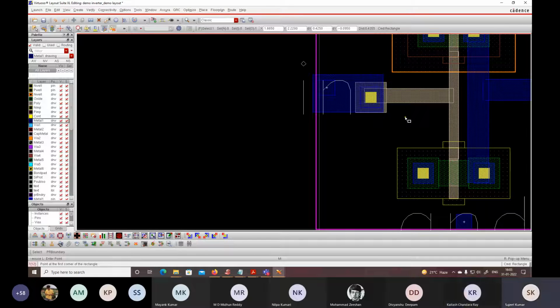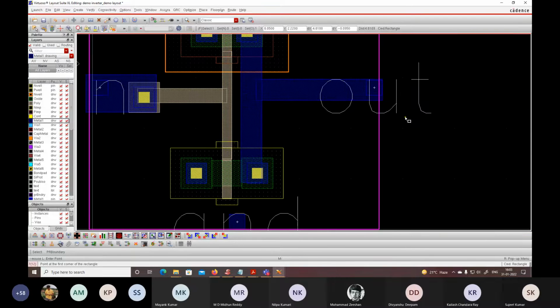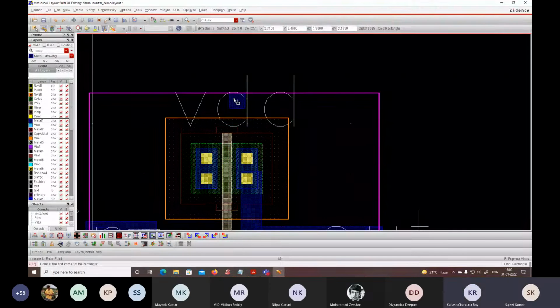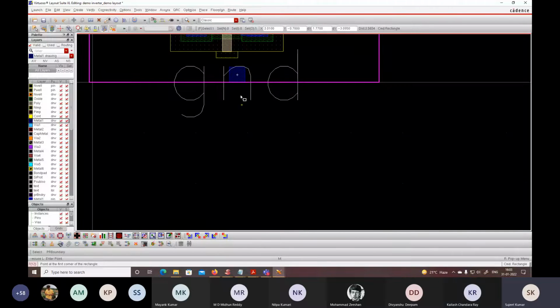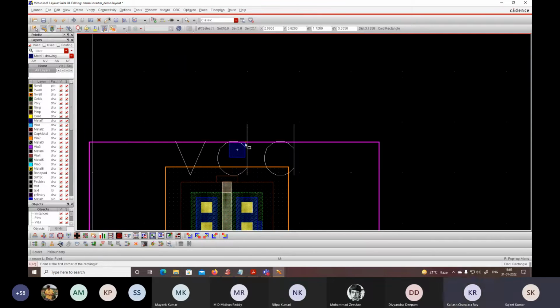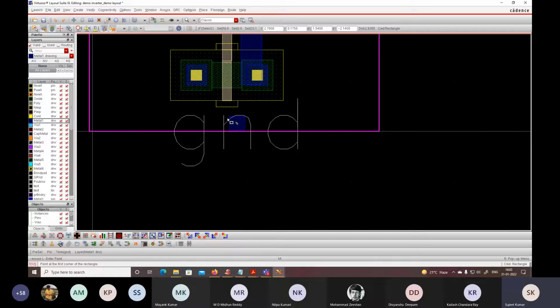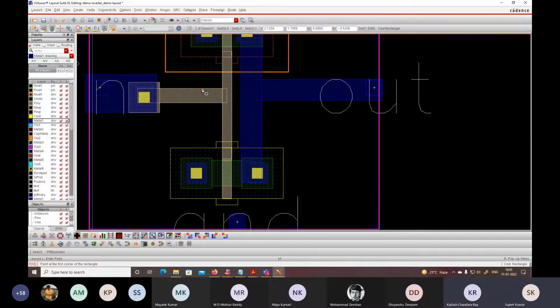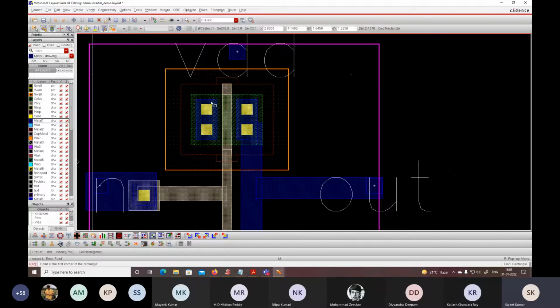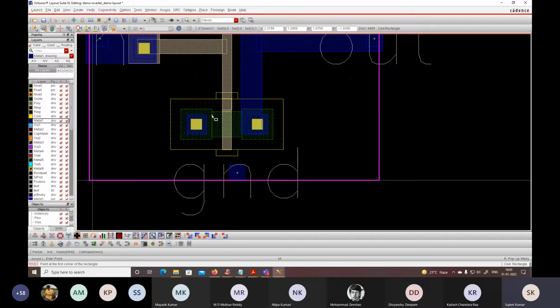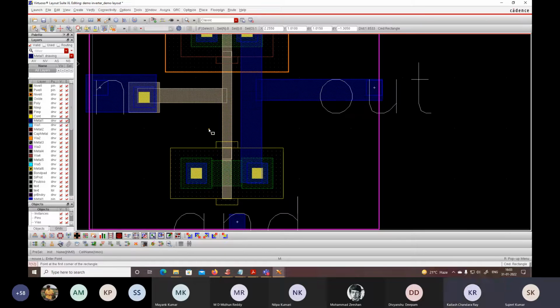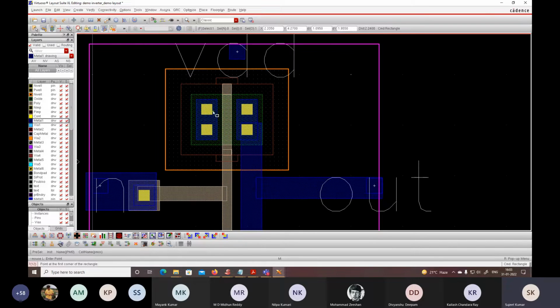Okay sir. So now we are going to connect our VDD and ground. So our VDD is of layer metal 1. So we are going to connect VDD and ground for each metal 1 layer here. Also our substrate is not here because in the circuit we have used the body. So the body is not available here, so we have to invoke the body of this too.